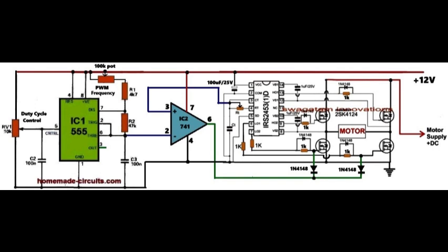The inverter section. In this stage, the IC IRS2453 is configured as an H-bridge, full bridge inverter. It generates a square wave output, where the frequency is determined by the external components RT resistor and CT capacitor. The motor is connected to the output of the H-bridge, and its speed can be controlled by varying the frequency of the inverter's output. RT is made adjustable using a potentiometer, enabling precise frequency tuning.